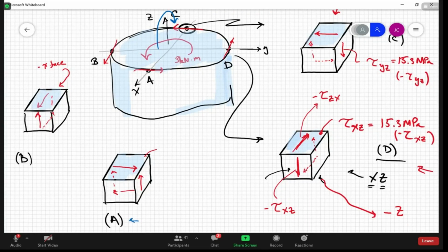How does that bending stress show up on the differential element at point A? Like a tensile stress? Tensile stress, right? Is it positive or negative? Tension or compression? Tension. Tension, right. Okay, so what type of stress component should that be? It's going to go this way, right? We know it's going to go this way. And on the negative face here, it's going to go that way, right? And that's from the bending. I'm trying to use the colors to denote what they come from, so I don't have to make it too messy. What component is that?